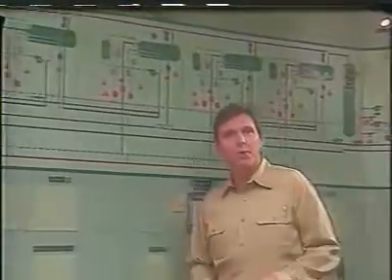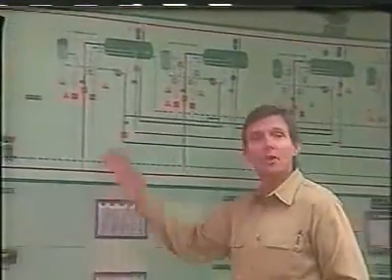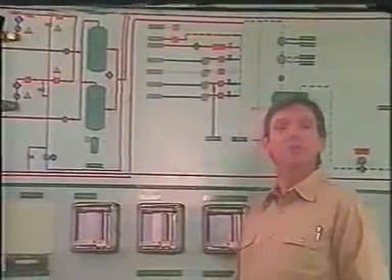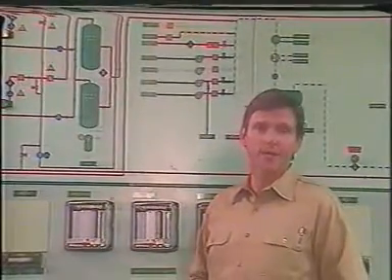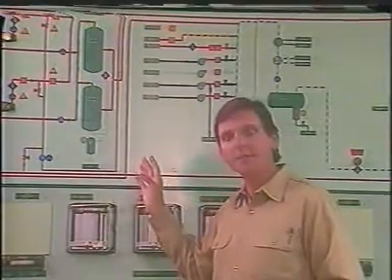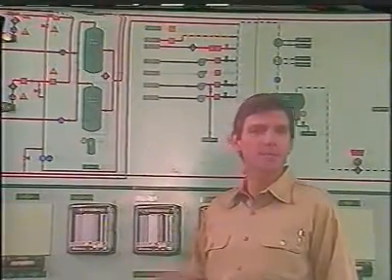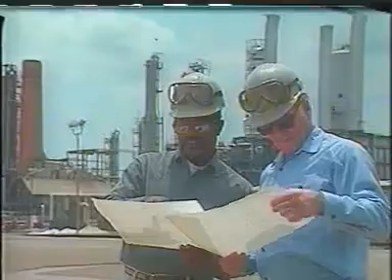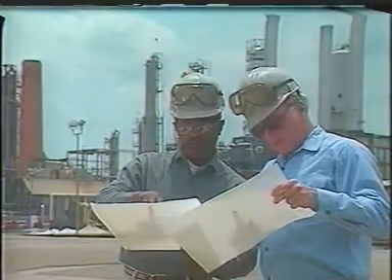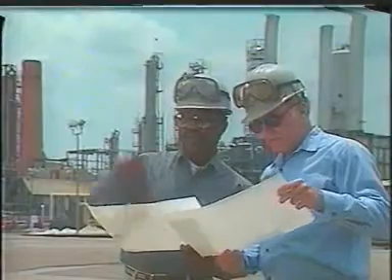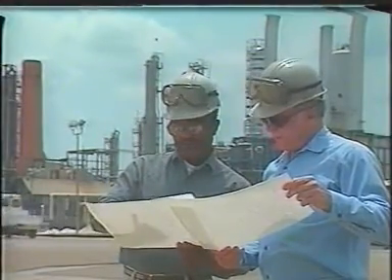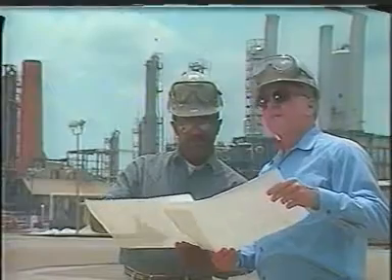Some process control rooms use charts to show the flow of materials entering and leaving a process. They also show where instruments and valves are located and how control loops are arranged. This kind of chart is often referred to as a process graphic. A process flow sheet of this type is used by contractors when process equipment is installed, and it's used for reference by maintenance and operations personnel after a process is put on stream.